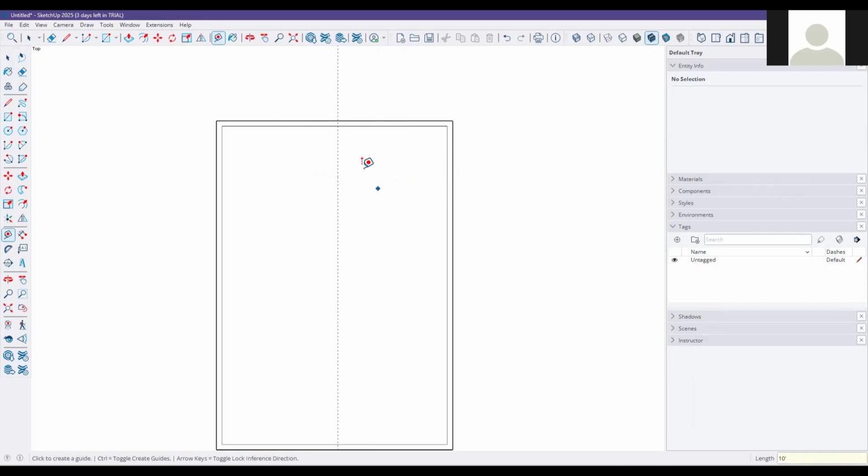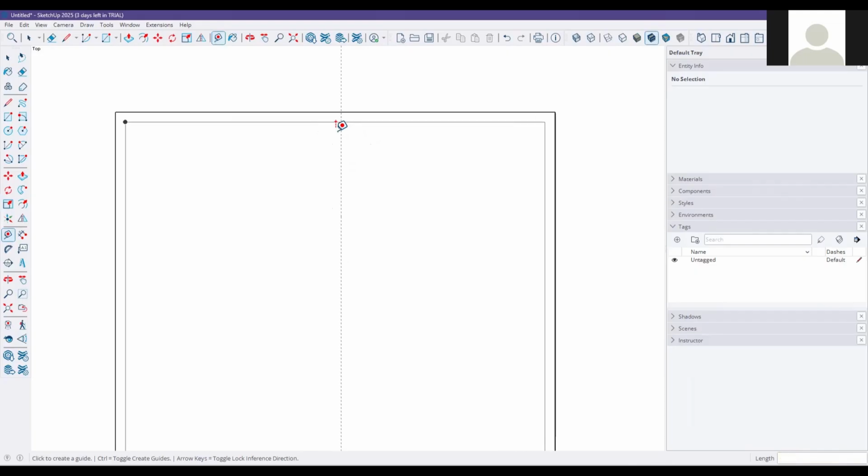That's it. And you created one guidelines here, right? You created one extra interior wall here. And then after that, you'll see how much the thickness for the interior walls would be. It's going to be 4 inches. So I'm going to drag again one line from here and type 4 inches and hit enter.